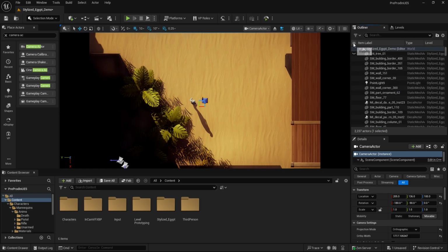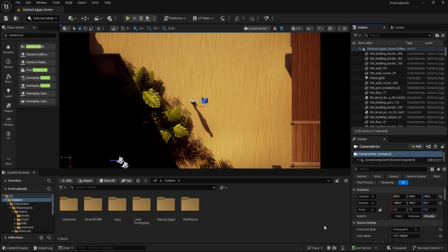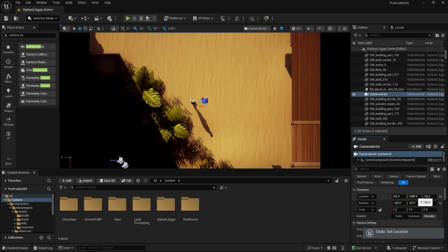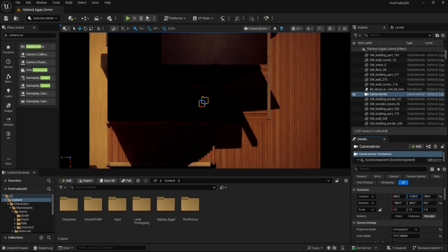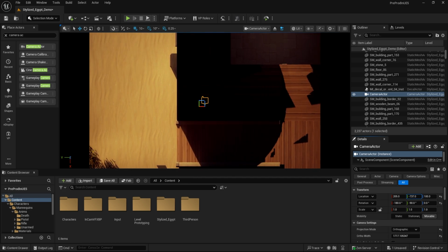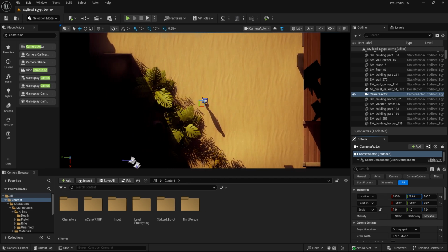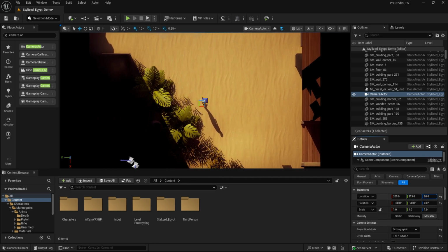While this is convenient, it can also lead to assets being fully removed where we only need to actually remove the top of them. For example, if I was creating a scene within this building and I wanted to create a floor plan image for it, I may have to toggle the visibility of the entire building, functionally making the floor plan useless. On the other hand, with my orthographic camera, I can change the Z position and this will almost cut out assets at certain heights within my level, allowing me to look inside of buildings without having to hide assets.